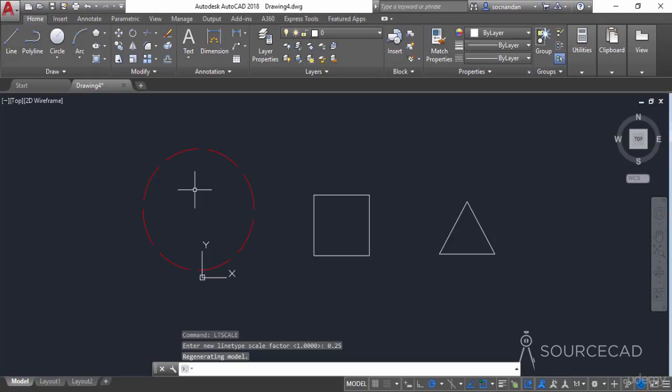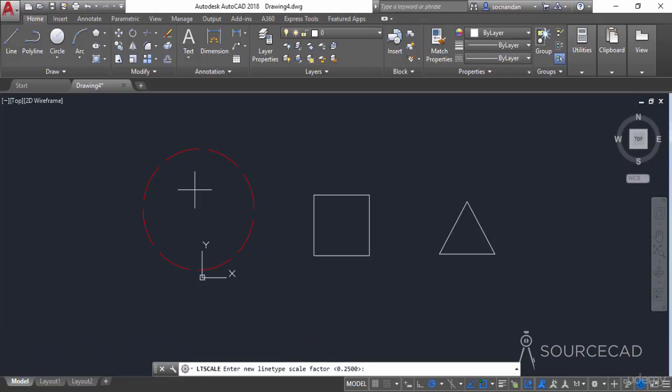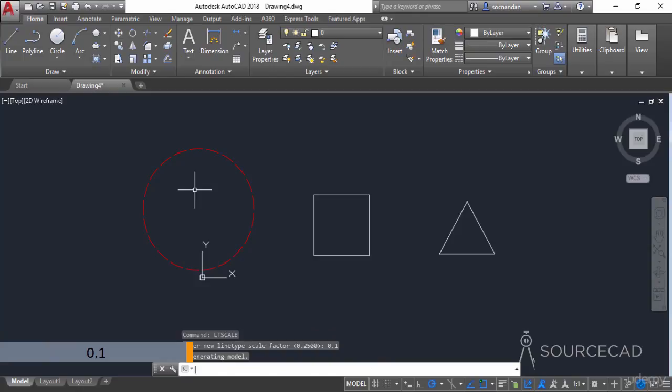In this case, we are not changing the scale from the properties panel, but we are changing it using the LTSCALE command. So once again, I'll type LTSCALE and change it to 0.1, and that looks quite appropriate. So you can use this also to change the line type scale of all of the geometries which are present here in the drawing area.